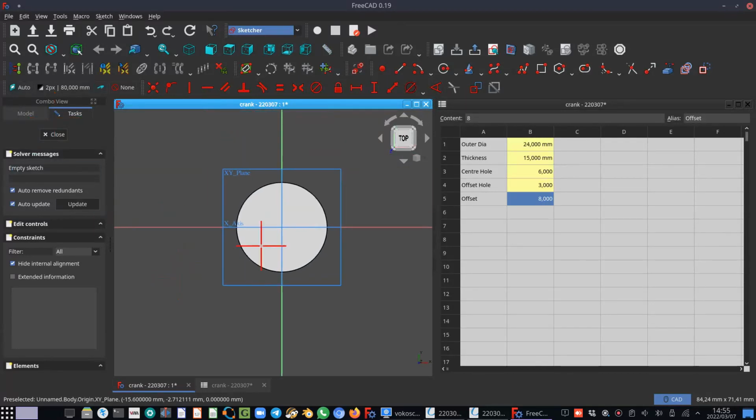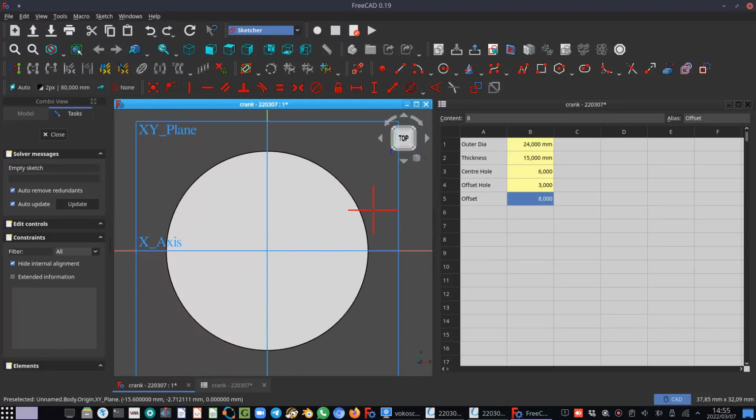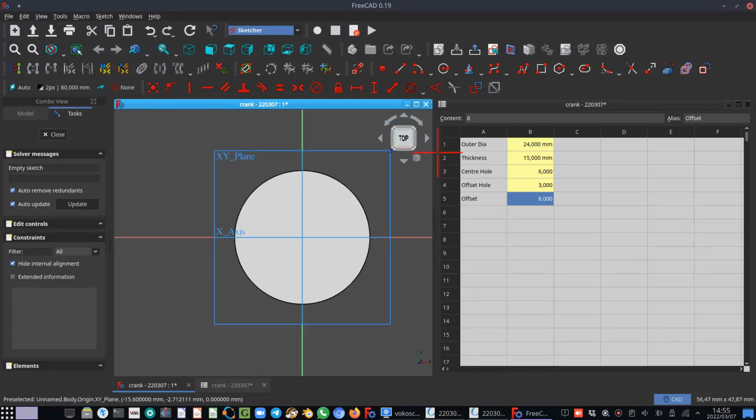Okay, so what we will do now, alright, over here is an icon in the Sketcher workbench that's very important if you work symmetrically as I've just suggested. What this does is, when in edit mode, switch between section view and full view. So what you see at the moment, we're looking at the sketch plane, but there is 3D geometry between us and the sketch plane. Now if you click on this icon over here, then we're looking at the 3D geometry in section view.